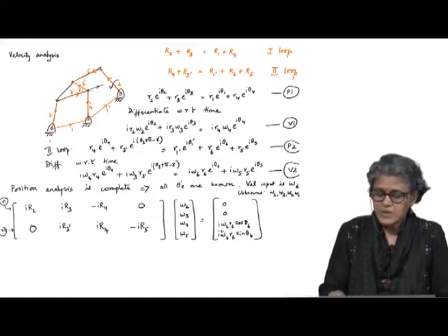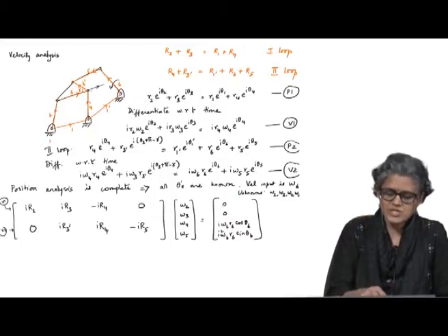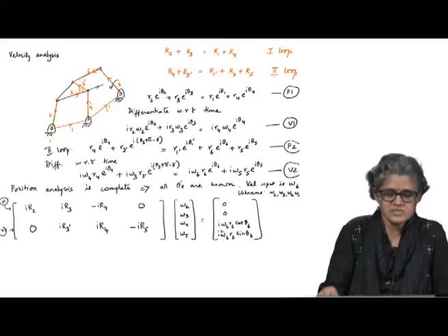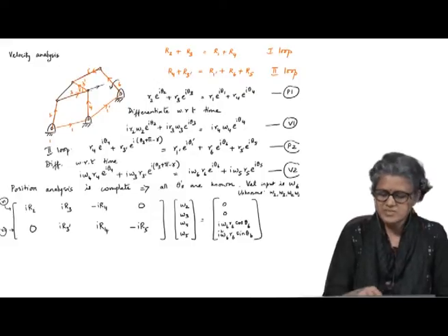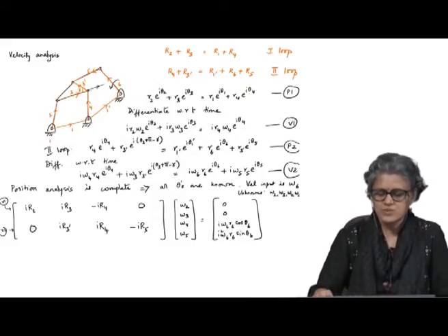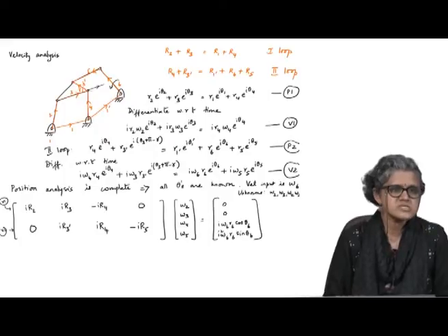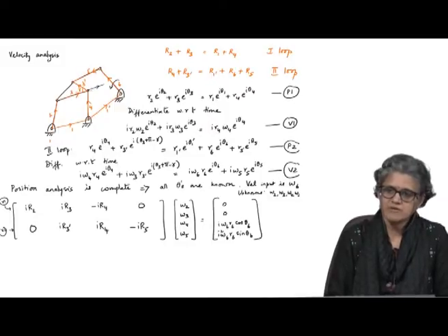So, I would equate. Each of these is 2 equations. Instead of splitting them up and writing in terms of cos and sin, I have just put it in vector form. Okay, but this is 2 equations, this is 2 equations, 4 scalar unknowns. I can solve this for omega 2, omega 3, omega 4 and omega 5, simultaneously.